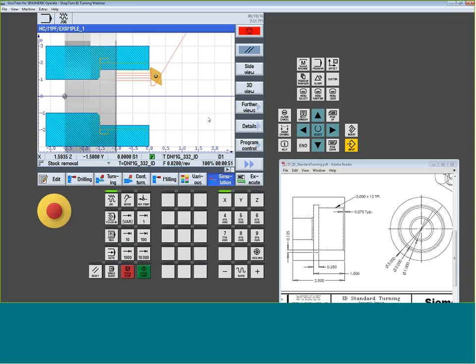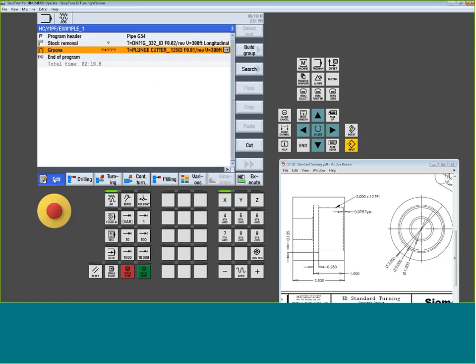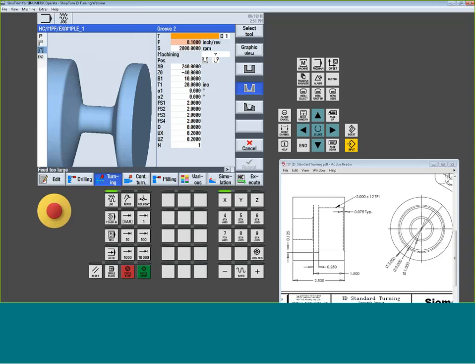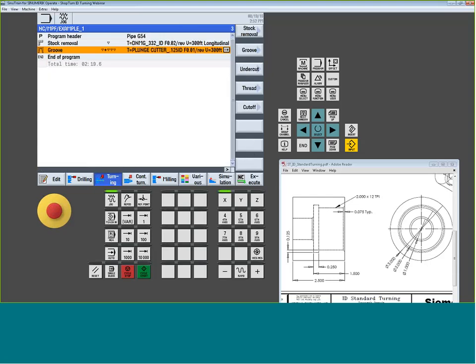So now we're turning, as we saw. Tool comes in, builds it. Now, I could have used a slightly different grooving cycle if I wanted to do a corner break on this edge. So back here in groove, if I use this grooving cycle, now I can do corner breaks on all my 4 corners. So I could just pick one of the 4 corners had I wanted to, maybe put a nice chamfer for that thread. But we just use a standard square groove for now.